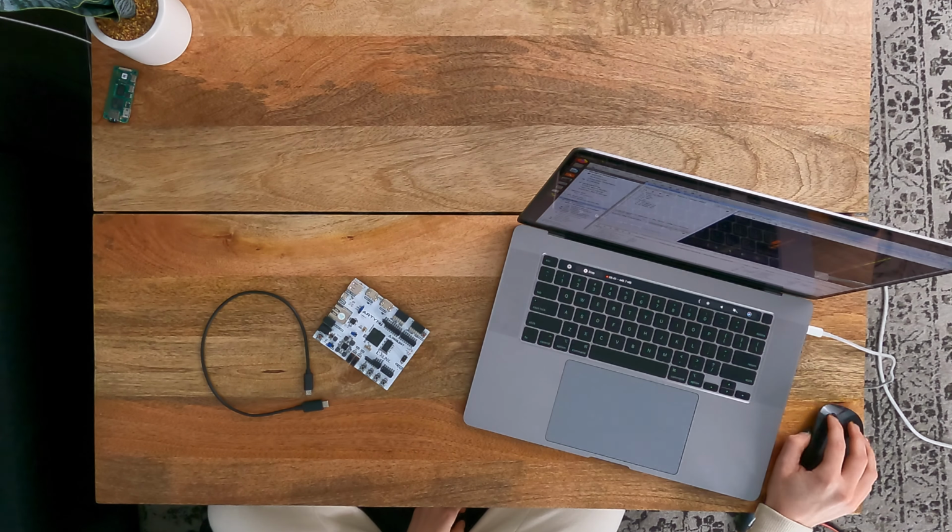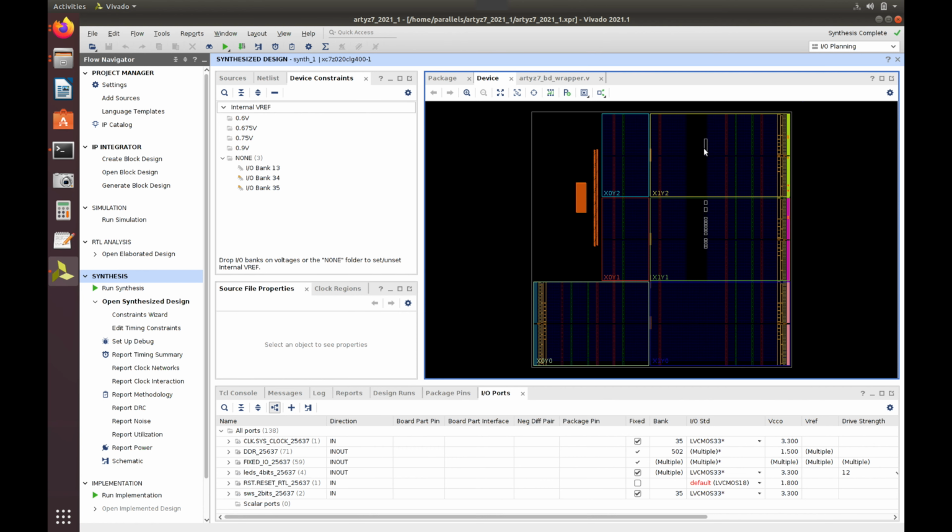So we've got a few different banks here. It is worth noting in the Zynq FPGAs, all the different banks have their own voltage rails connected to them. So if you have a certain voltage rail set on a particular bank, all of the pins have to operate at that voltage. So if you set that voltage rail for bank 14 to 3.3 volts, all of your I/O connected to those particular pins connected to voltage bank 14 all have to operate at 3.3 volts.